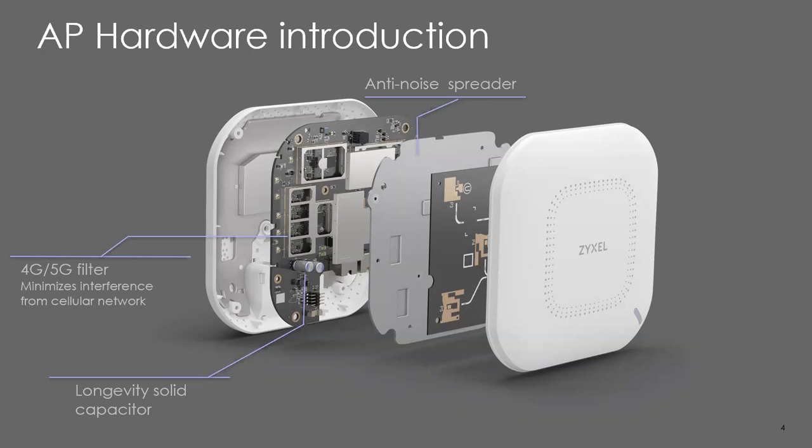So when we're looking at these types of products, one of the challenges we run into is there's solid states. There's no moving parts that could break, but there is failure over time. So our design has been taking that into account to try to minimize that. And this is the reason why we can offer a lifetime warranty on our $100 access points. So one of the leading causes of failure on these guys here is what we call heat fatigue. Heat builds up inside the units. The chips themselves get warm, and that can cause the little switches in your microcontrollers to fail. Heat can also cause problems with the solder, giving you cracks in your solder joints.